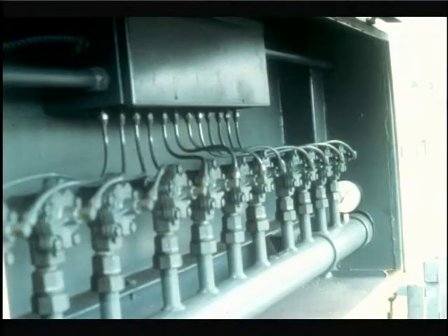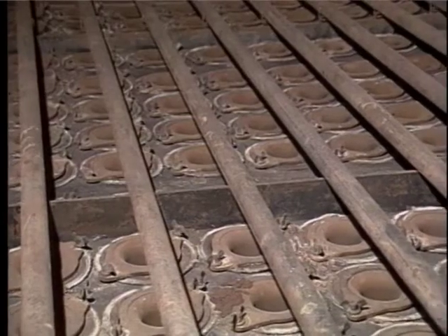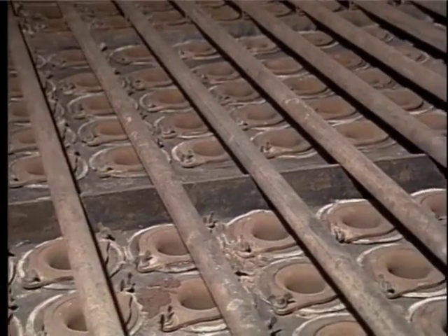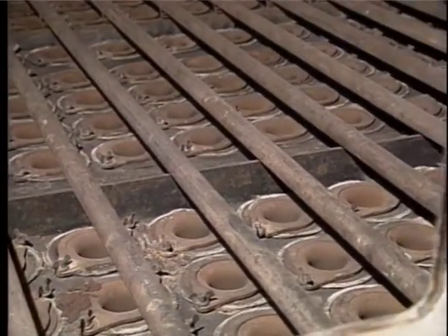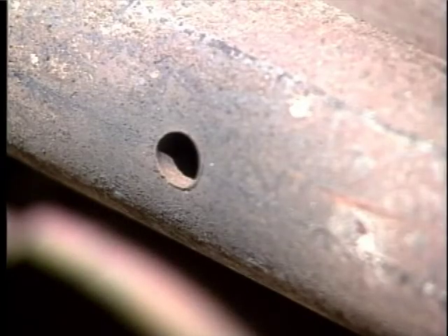The solenoid and diaphragm valves sequentially deliver the compressed air from the storage manifold to the lateral pipes or blow tubes that are located just above the tops of each row of bags. The laterals have small holes in them that direct the compressed air into the center of each bag.